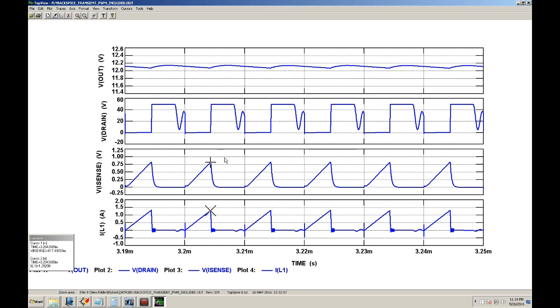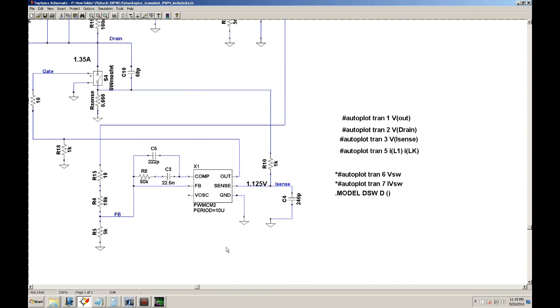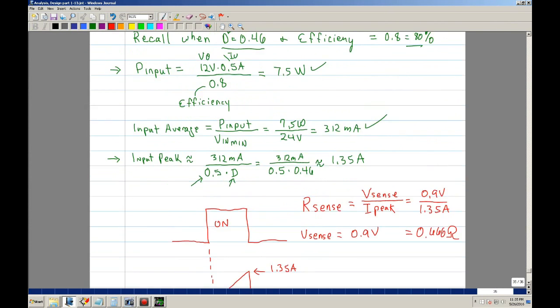So that looks very good. Now you can tell that it's regulating, and you have enough margin that if you need extra power, it will provide that power because you have a margin from 1 to here. So basically you have 20% margin, which is good. So that's one way of setting the current sense resistor, which is this part.